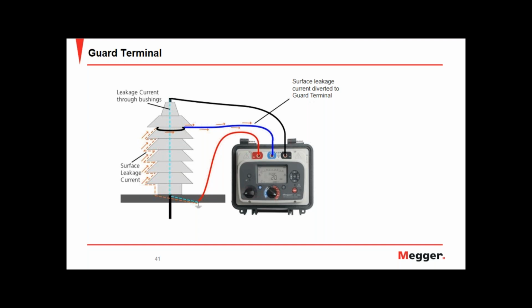We also have, where we have multiple insulators and multiple leakage paths, a kit where we can link up all these assets together and take them back to the guard terminal, so we can remove all surface leakage effects and eliminate them from our measurements.